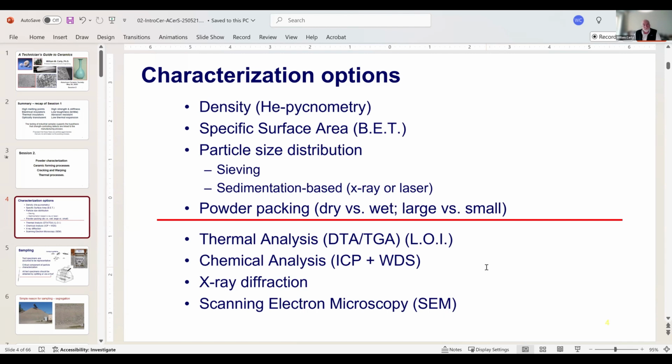If they're lucky and they're things like clay, they can just put them in water basically, and the particles will deagglomerate and you get slurries. No particle size reduction is necessary. In fact, in those systems, they might remove the coarse particles through a sieve process or through an air flotation process or hydrocyclone or something like that.